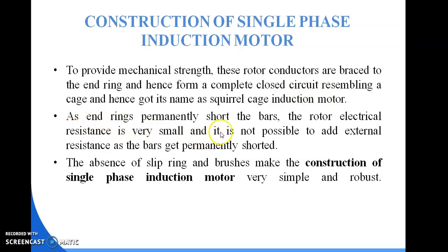As the end rings permanently short the bars, the rotor electrical resistance is very small and it is not possible to add external resistance as the bars are permanently shorted. The absence of slip rings and brushes makes the construction of the single phase induction motor very simple and robust.